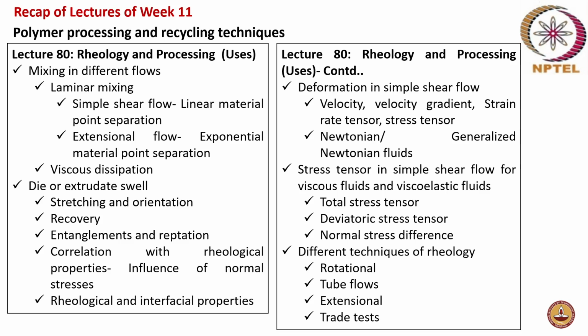Next, viscous dissipation was discussed. And then there was discussion on die or extrudate swell. So, what are the macromolecular reasons behind this extrudate or die swell? Stretching and orientation, the recovery, entanglement and reptation. And then, what is the correlation with the rheological properties? So, what is the influence of the normal stress, especially for a die swell of a polymer extrudate compared to that of a Newtonian fluid extrudate? A correlation was shown. And then for the rheological and interfacial properties, there was a small discussion.